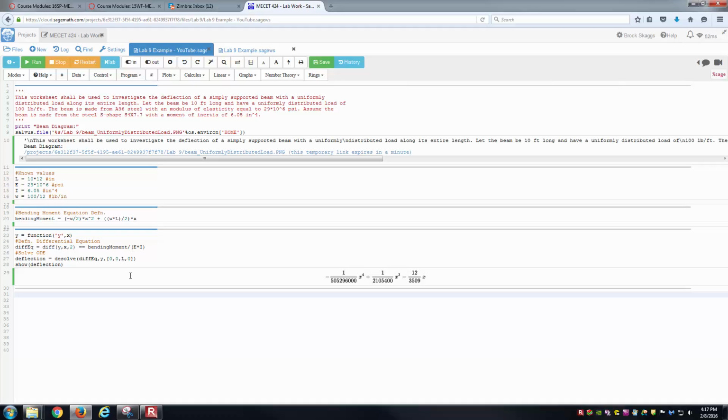And so let's test this a little bit. One thing we could say would be to look at specific points. And so let's do that. Deflection of beam at a specific point. And so to do that, we could use the print line. Say, okay, let's print deflection at x equals, say, the midpoint L over 2. Expect the maximum value to be there.